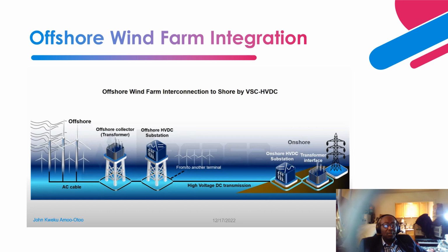Next is the typical configuration of how an offshore wind farm looks like, and all the components that it encompasses before its power is exported to the onshore facility. Right. Okay. So you have a wind farm consisting of many wind turbines that are arranged in different arrays, different configurations, and the most popular arrangement is radial or radial star. And sometimes you can have a loop for much more reliability. But that itself translates into higher cost, as you form those loops; putting all that redundancy in is more cost.